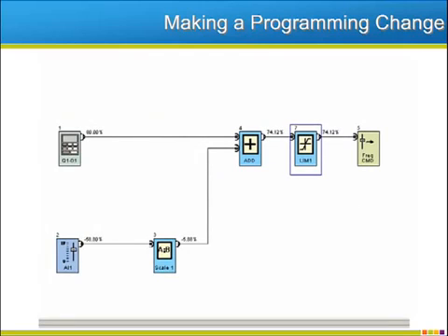After a programming change, recompile, download the updated program to the drive, and continue monitoring. I have changed my main reference in the keypad to 20%, but due to the limiting function block, my frequency reference to the drive is 40%.